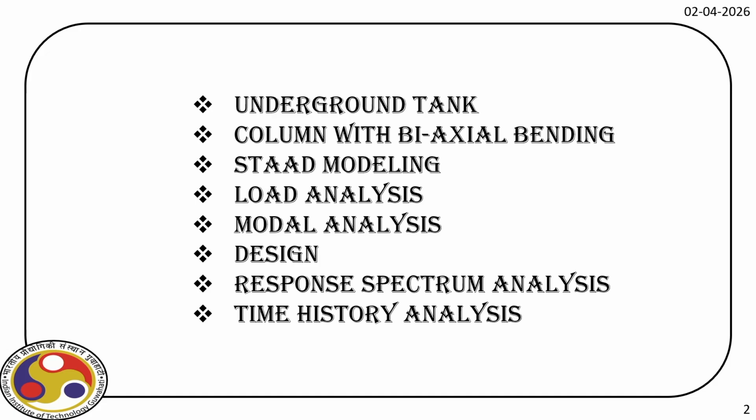This is very important for seismic analysis. For that, first I will introduce the concept of response spectrum and how we can use the design response spectrum given in our code to analyze the structure. Again, we'll not go into the details of theory, but I will broadly introduce you to the concept of response spectrum and how we can use the design spectrum for the analysis. Finally, we'll go for time history analysis.